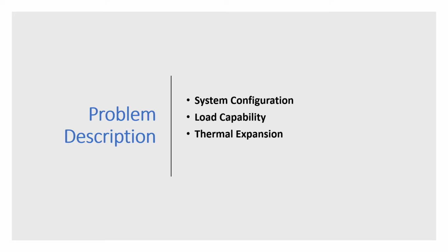Second comes load capability. When any robot is manufactured, the payload of the robot is one of the most important specifications in it. It determines what tools and objects that the robot can carry at any point in time. Typically, the load of the robot is calculated when it is in the fully extended position. Payload can also be calculated as minimum braking load divided by the safety factor. Moving on to thermal expansion.